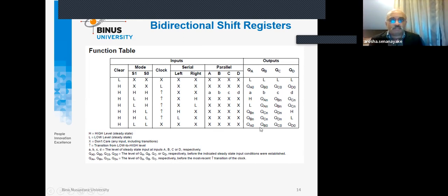Importantly, you have to understand that S0, S1 governs whether left shift, right shift, parallel, or no operation occurs. That's what you can see in this table.